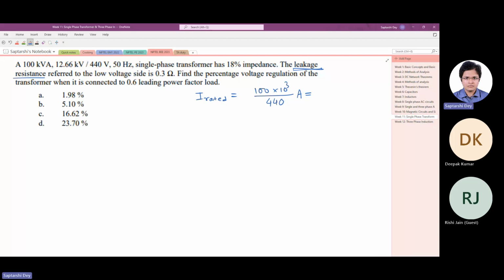So you studied power transmission, power system. There also it is used a lot. Basically, it is to give you a general idea of the impedance values, because if you look at transformers of completely different ratings, their absolute impedance values will be different. But per unitized, they will be more or less comparable. Okay.